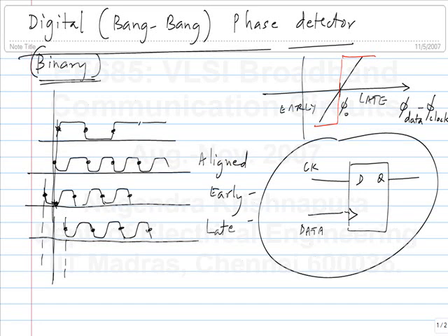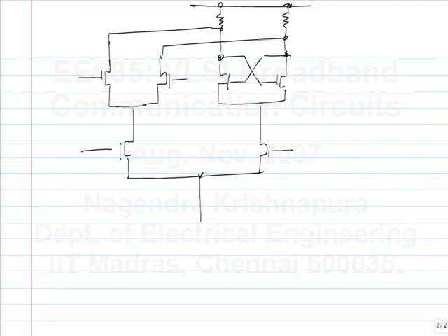So the other disadvantages: yes, this is a phase detector and I think it works, except that there is the slight practical problem. You understand this, right? The clock amplitude has to be good enough to switch from one side to the other, from the sampling side to the latching side. Now if you apply data here, that may not always be the case. But even besides that, you would like to have a clock and data recovery circuit. That is a single circuit that helps you find out the phase between clock and data, but also gives you the retimed data once the clock is aligned. So that it does not do.